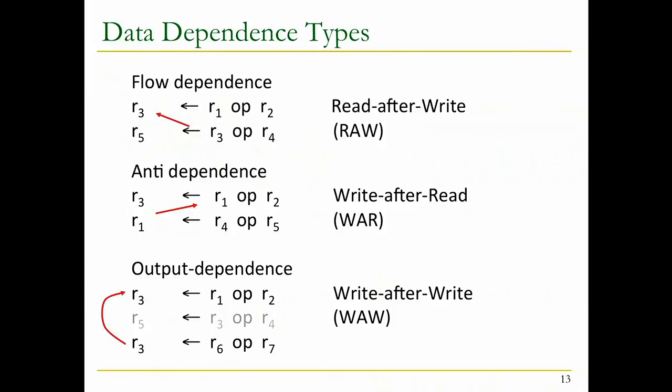If you execute this instruction earlier, there's one problem. You may not want to write into R3 because R3 may be needed by some other instruction that's going to be executed later because its value is going to be produced later. So maybe you store this somewhere else. And you can store somewhere else because these really have nothing to do with each other. They're just dependent on a name because the compiler didn't have enough registers. Okay, so that's called register renaming, and we'll talk about that when we get to out-of-order execution. But the fundamental reason you can do that is these two things are really specifying a name, there's no value dependence. Okay, any questions?